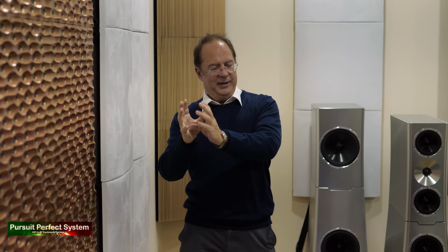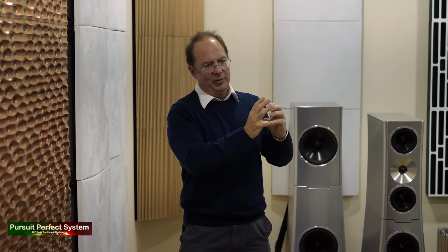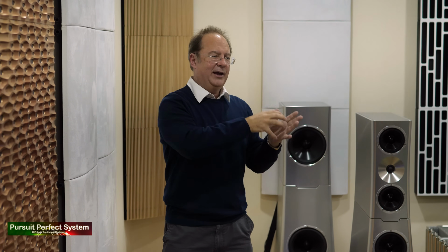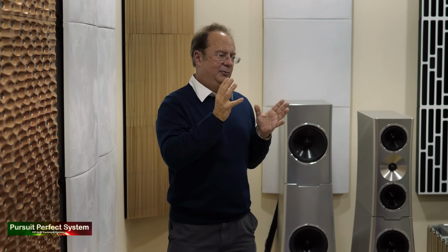The thing is that even though you think the transparency and the detail resolution are better because you've got this noise pumping up and down with the signal, when you listen to the timbre of each instrument, you'll find saxophones also sound brighter. And that's not right. Saxophones should sound rich and dark and smooth. So the minute you check for timbre variations, you'll find that the detail resolution seems better, but the timbre variation is worse. And that will be a red flag to tell you there's something else going wrong.